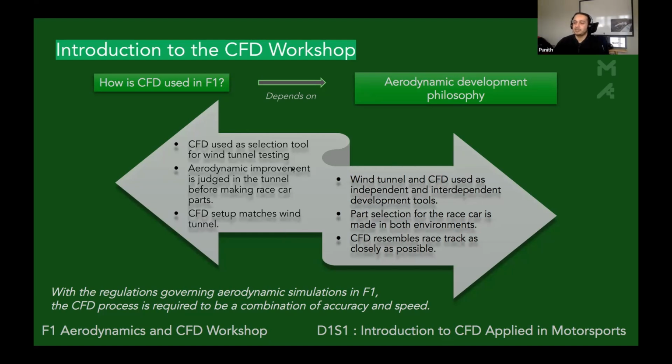I've been out for a couple of years, but this is the predominant philosophy at most teams. With the regulations that the governing body imposes on simulations in F1, the CFD process is required to be a combination of incredible accuracy and speed, and that comes into play later when we talk about why we do only steady state simulations and things like that. So it's something to keep in mind.